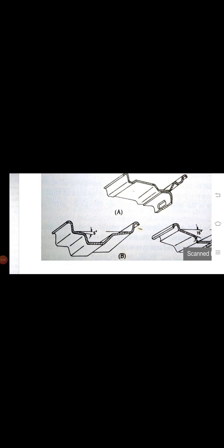These rims have high wall flanges which protect the tire bead and wall from damage due to external interference. Generally both tubed and tubeless tires are fitted on these rims. However, large section tires cannot be mounted over this flange, and hence these rims are only used for vans and small commercial vehicles. So this is the van 5-degree seat angle wheel base rim.